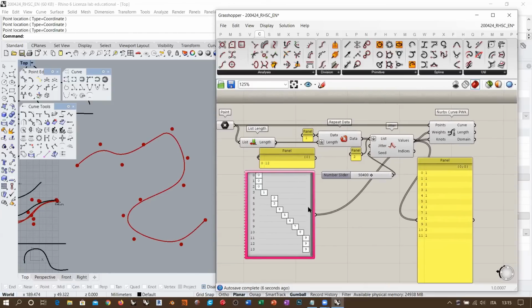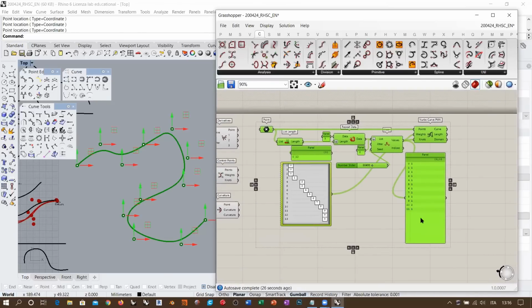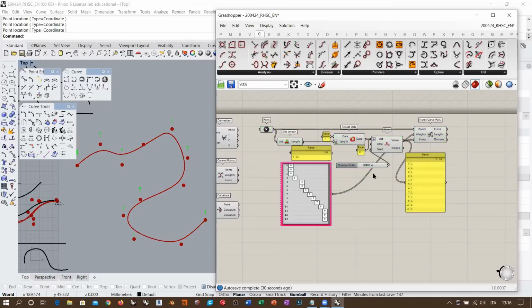So now I have a non-uniform curve, because the knot vector is non-uniform because of this double knot that I have here, the 3, and it's rational because I have not the same weight for all the control points, okay? So this is what you must do if you want to make sure that you understood exactly all this non-uniform and non-rational or rational stuff, okay?